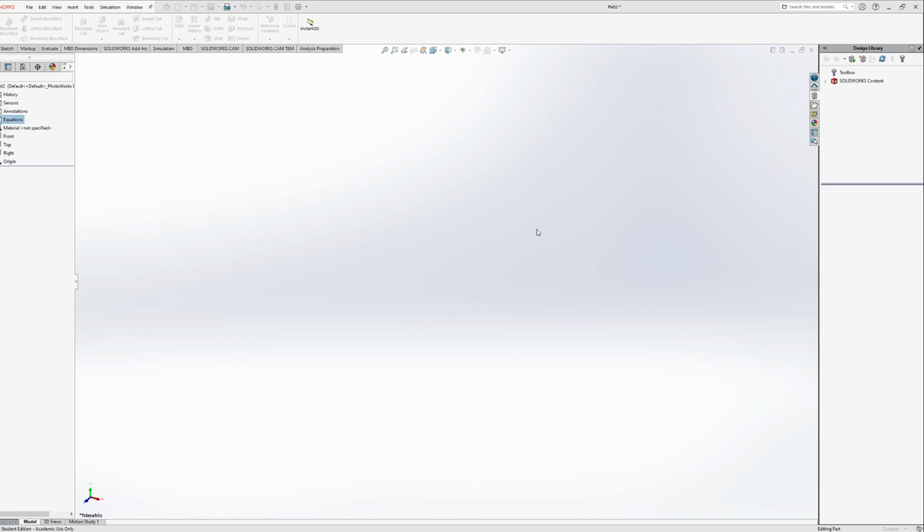So in that values slash equations tab, we're just going to make it, I believe it's 20 millimeters. So if you add the mm or millimeters to the end of your 20, it will specify that that is a specific measurement rather than just a constant. I wouldn't say it's entirely necessary, but it is good to add just to ensure that things are consistent. And if I am looking correctly, yes, we are dealing in millimeters. So we'll just input all of those constants that are there.